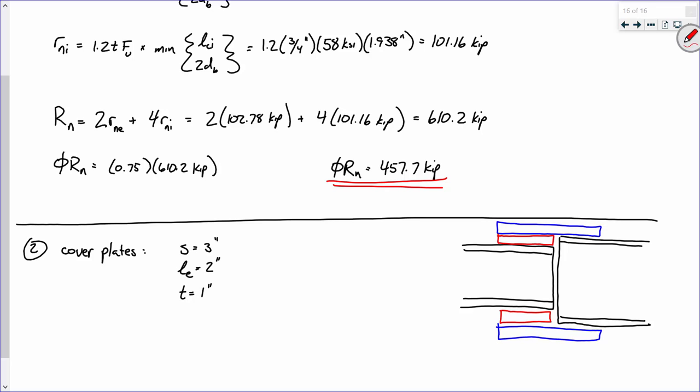Well, what I'm getting at is, think about this. When I yank on this, think about how the load's being transferred. I've got a load on this member. That load is going to these bolts, so it's going into this plate. And then that plate, the bolts are ultimately going down here. I mean, yeah, you can develop some friction forces here and there. And when we do slip critical connections, we do have factors where we have to consider how many filler plates we have. But by and large, they're not structural like the cover plates are.